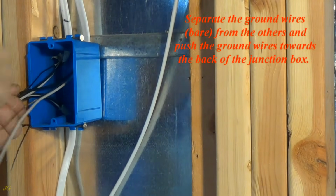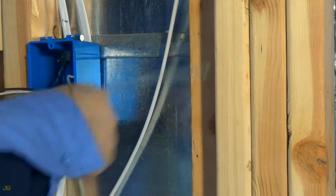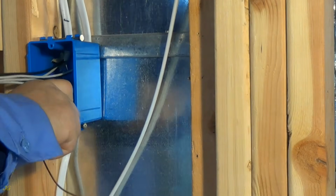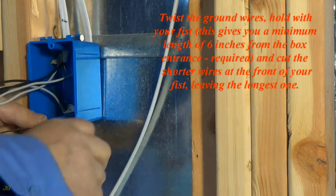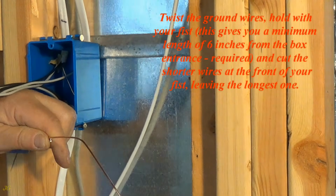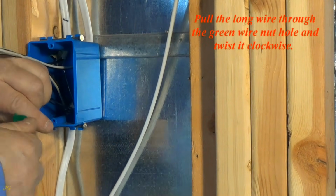Separate the ground wires, bare, from the others and push the ground wires towards the back of the junction box. Twist the ground wires. Hold with your fist. This gives you a minimum length of 6 inches from the box entrance, required, and cut the shorter wires at the front of your fist, leaving the longest one. Pull the long wire through the green wire nut hole and twist it clockwise.